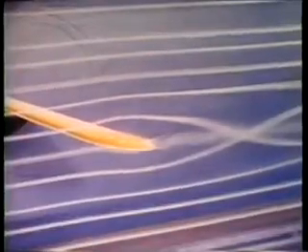This is of considerable consequence because it sets up violent whirlpools of air called vortices, and one of these disturbances could last for as much as several minutes in the air. A vortex like this one is an invisible hazard, especially around busy airports where large, heavy aircraft form them during takeoff and landing. They are the reason we always try to avoid the known paths of large, heavy, arriving and departing aircraft.